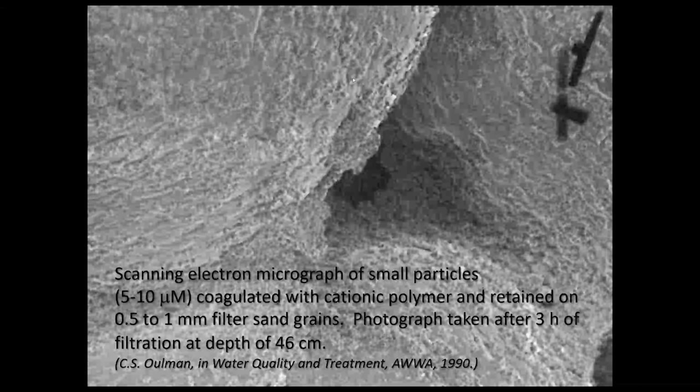And all these little tiny fuzzes, or whatever you'd like to refer to them as, are actually the turbidity that we're removing. And so you can see this is a giant chasm, basically, where these tiny little particles would have no problem at all flowing directly through there and not being removed by the filter if they hadn't been conditioned and had their charges neutralized so that they would actually adhere to the surface of the filter media.